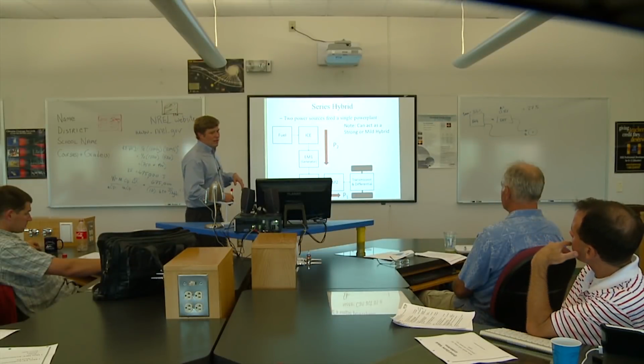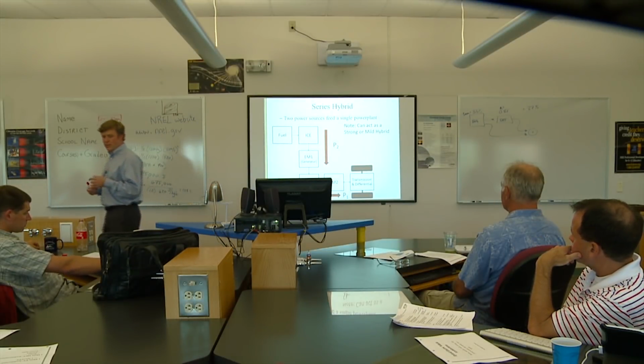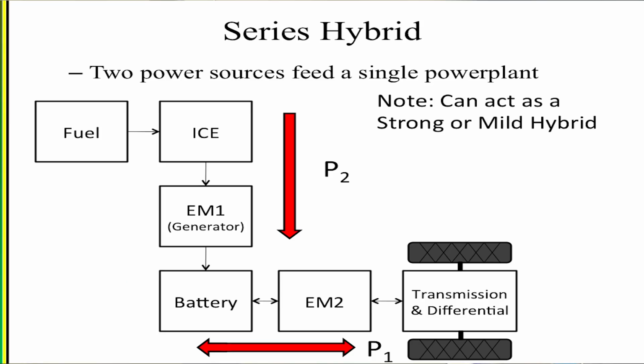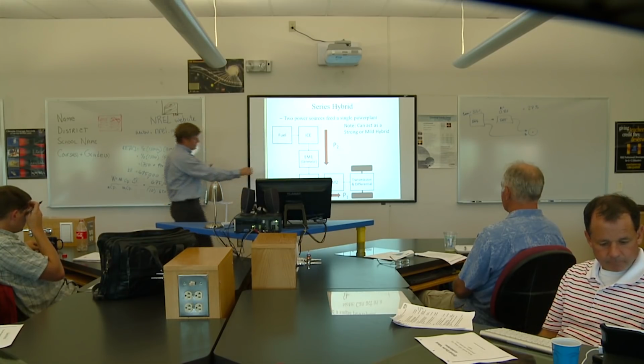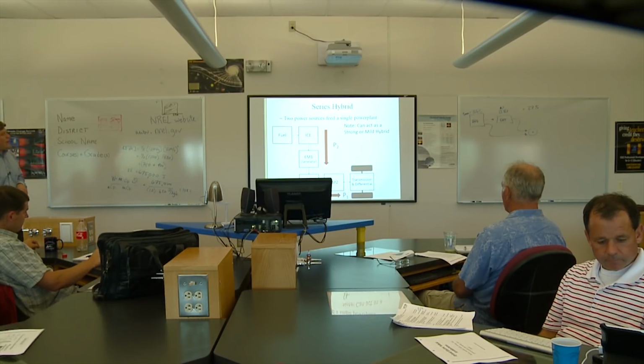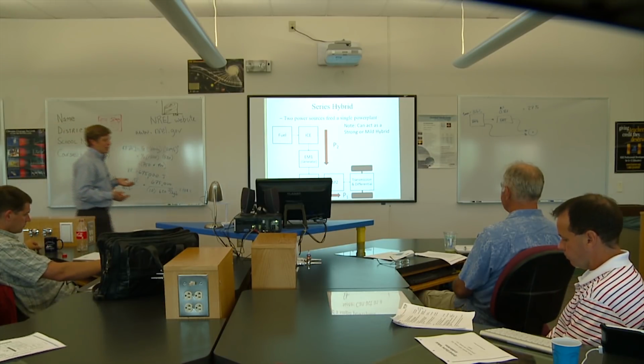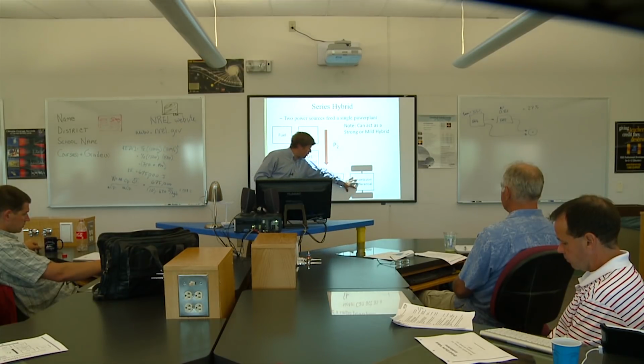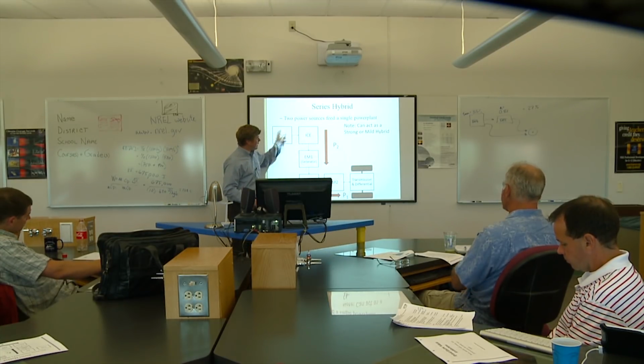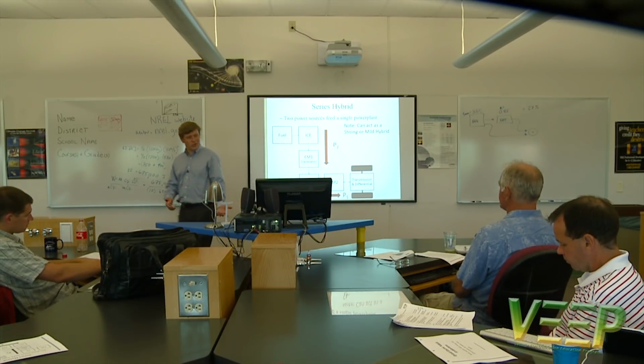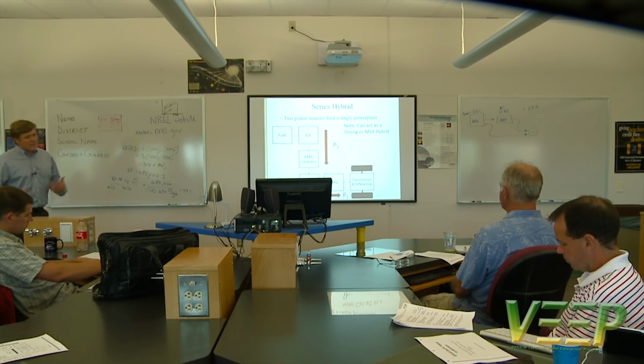The next idea is what is called a series hybrid. It's a series hybrid in that it has what you'd call a series connection between these two power flows. There is a mechanical power flow, basically a rotating shaft here, and an electrical power flow, and they're connected in series, one after the other. The global idea is this looks a lot like an electric car, where it's got a battery, an electric motor, and all that. The only difference is that this electric car, instead of being charged from the wall, is charged by this engine.